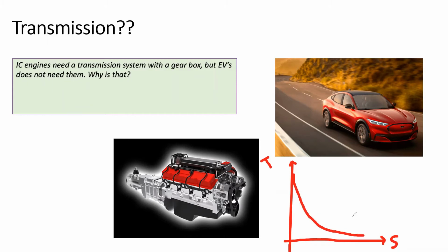At the beginning, at slow speed, that means 0 kmph, in order for the vehicle to move first, you need to apply more tractive force. But when you increase the speed little by little, the tractive effort you need to put on the ground, or the applied force, has to be reduced.